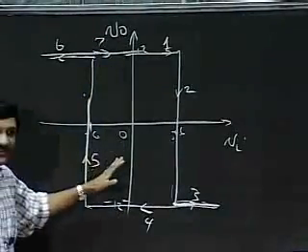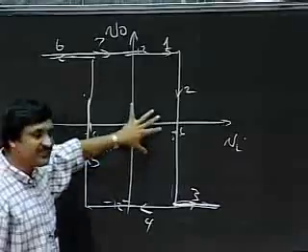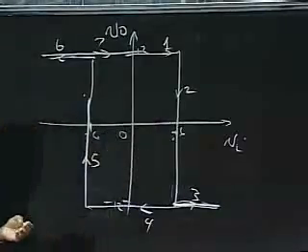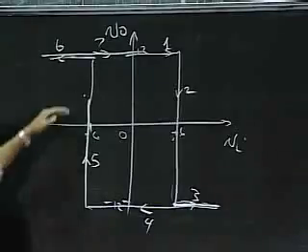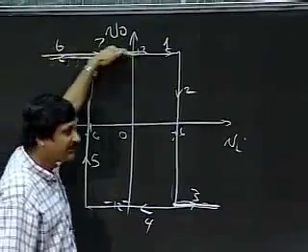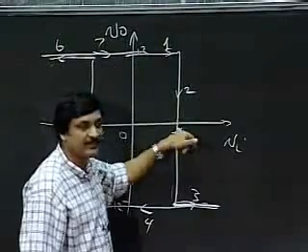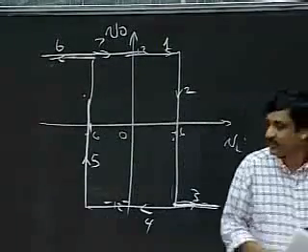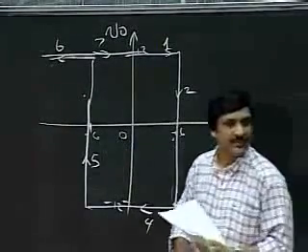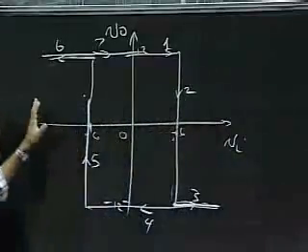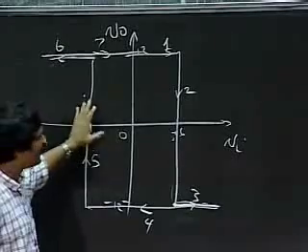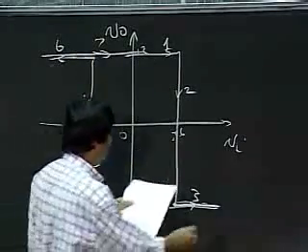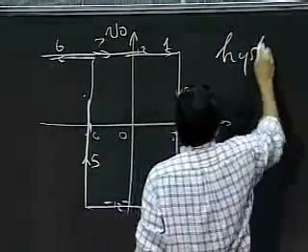What is spectacular about this is that I seem to have a circuit that now has some knowledge of where it came from. Okay? So if it's coming from here, it switches at plus 6. But if it's coming from here, it switches at minus 6. Okay, so there seems to be sort of a lag in the behavior of the circuit, or some memory property in the circuit. Okay, this kind of behavior is called hysteresis.